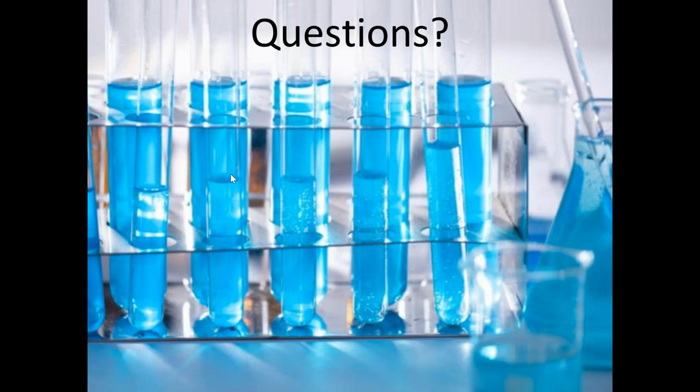We got a question. Yes, nitrifiers use up alkalinity. They destroy the alkalinity in the water. And one thing that I had meant to write down and didn't is that actually if you go through a denitrification process after nitrification, it actually puts the alkalinity back into the water. It undoes that alkalinity destroying effect.